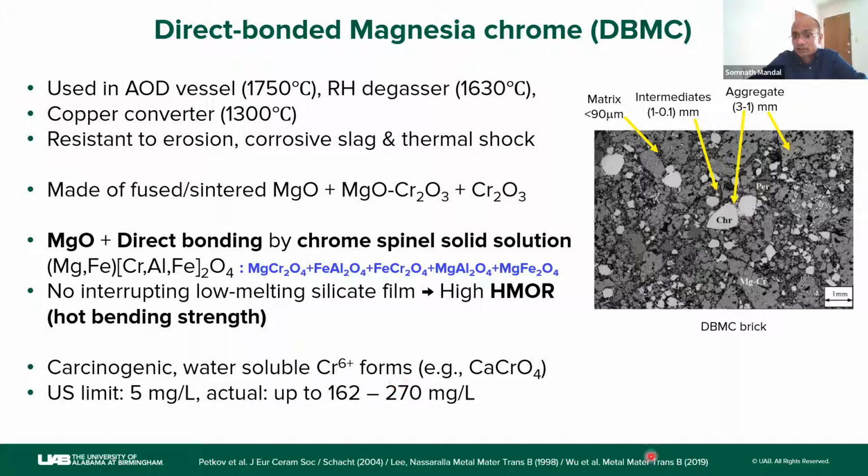There are reports where they have actually quantified the hexavalent chrome content in used refractories, and they have found 30 to 50 times the permissible limit. So this is a real problem. This hexavalent chrome is a real problem. It causes cancer. It contaminates the groundwater. So there needs to be a replacement. And actually, it has been replaced in cement kilns, which run at 1450 degrees C, but at 1600 degrees C and higher, there has been no replacement.